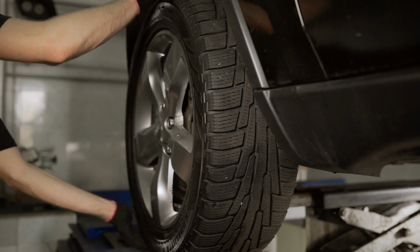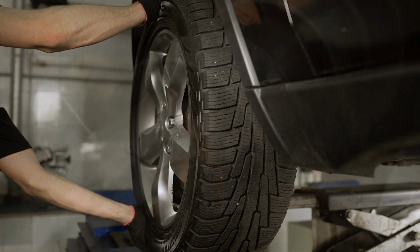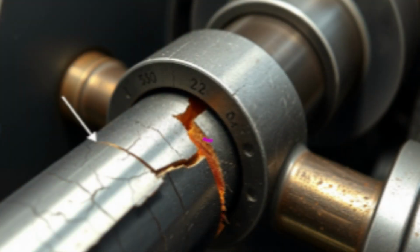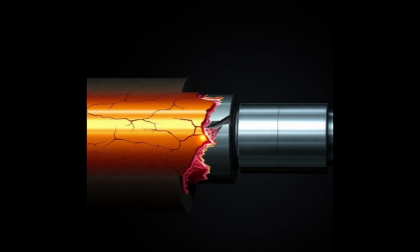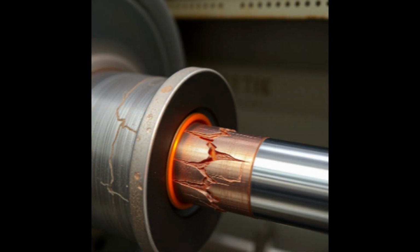Suspension components in vehicles, exposed to regular impact and vibration, are also susceptible. In addition, machinery like pumps, compressors, and turbines, which operate continuously, face fatigue stress in moving parts due to vibration and cyclical loading. Understanding and managing fatigue stress is critical to ensure the longevity and safety of equipment, as fatigue-related failures are often sudden and unexpected.